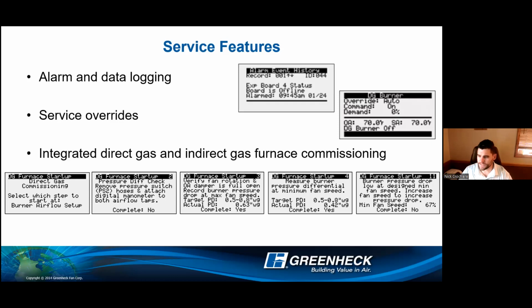Not only that, if you put in a value that's within the spec and you go to the next page, it saved it. Once you're done with the startup, you have a saved startup report with the date and time on that microprocessor. Anybody can come up, plug in, and download a PDF startup report. Now it's always going to be saved. So it's not a handwritten startup report. It's lost to the wind. No one knows where it was. Hey, I just know it was started up at some point. Well, now you can go up and actually check at the unit.